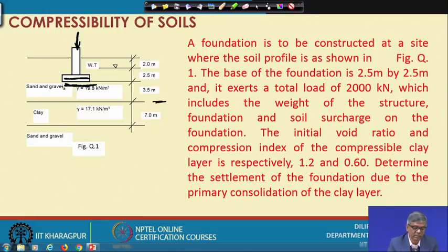One component is because of the elasticity of the soil material. This sand, because of its elastic properties, will have some compression, and this soil also, because of its elasticity, will have some compression. But the second part is this clay soil, which will undergo consolidation; this soil will not undergo any consolidation.